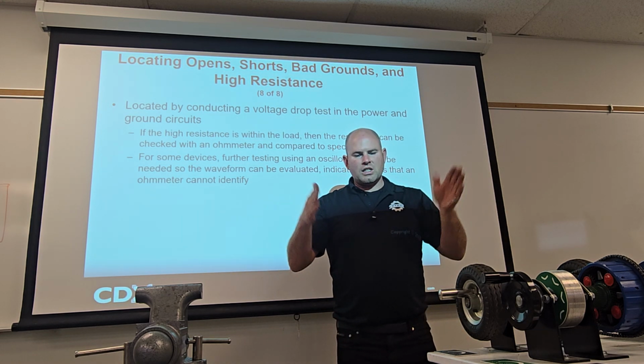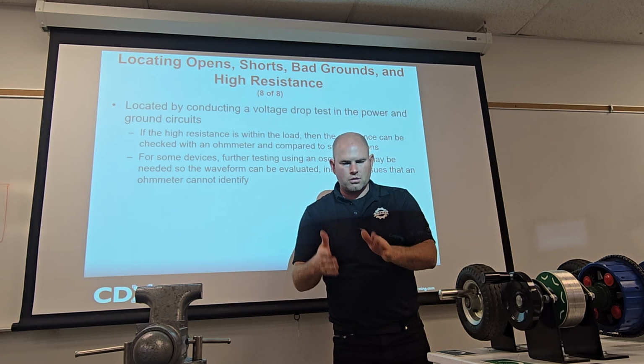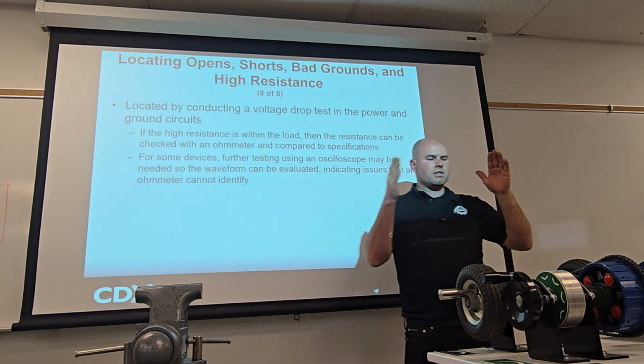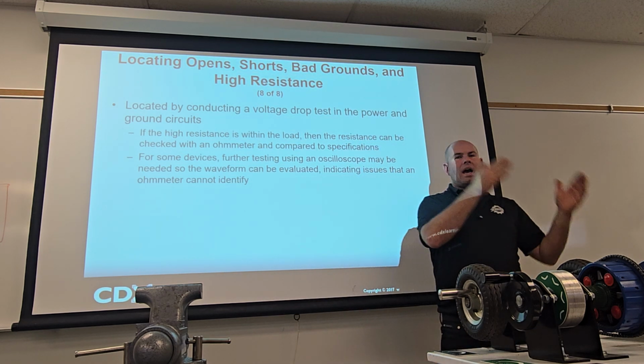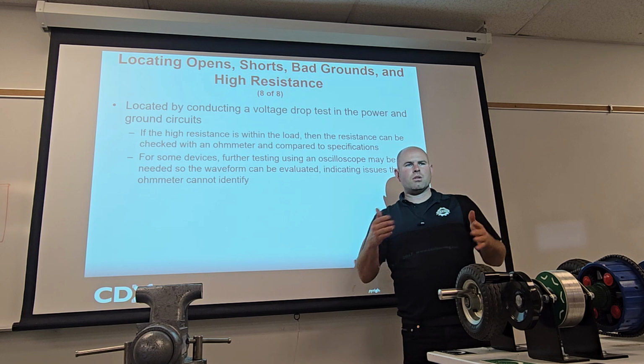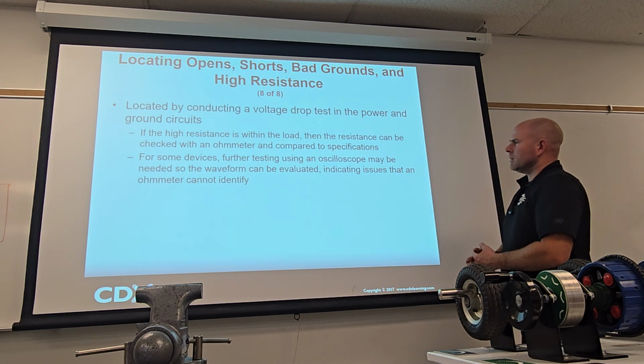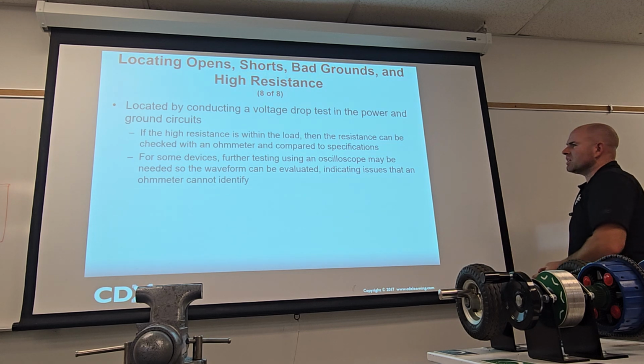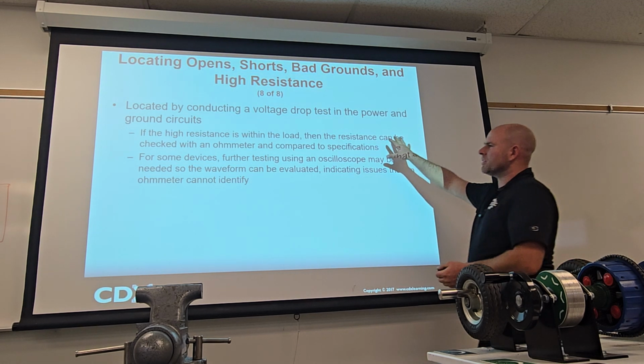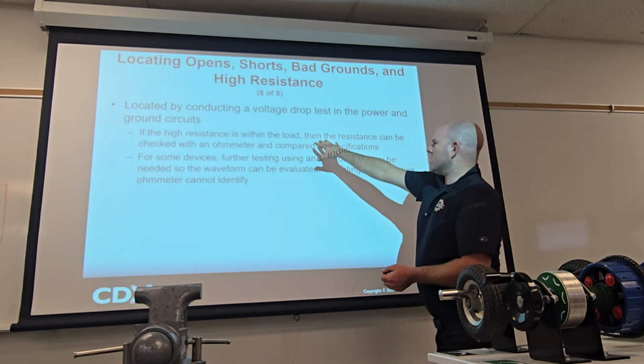Then you remember the steps. You'd move your leads closer together. Maybe test the solenoid. Maybe test this connector. Maybe test this cable. Maybe test the battery terminal, right? You could test the components and then prove which one's bad. Cool?